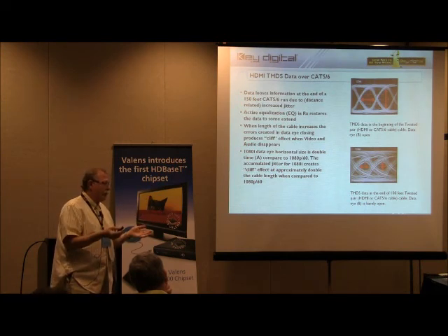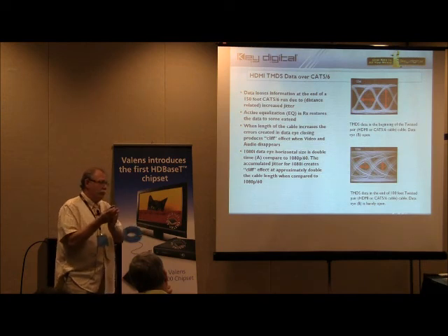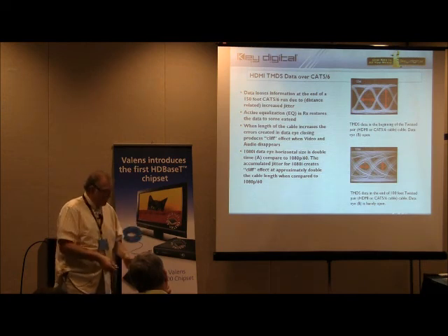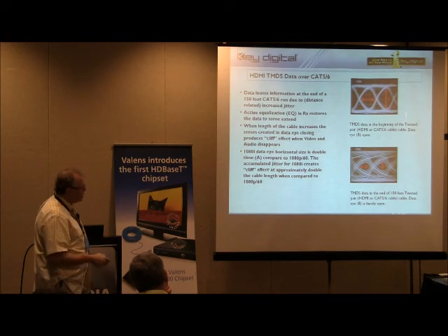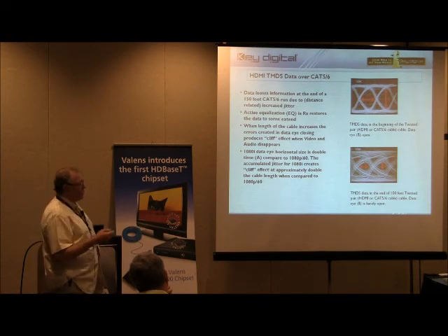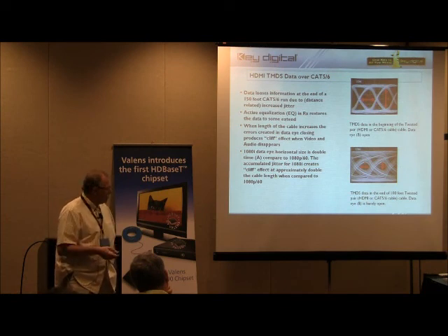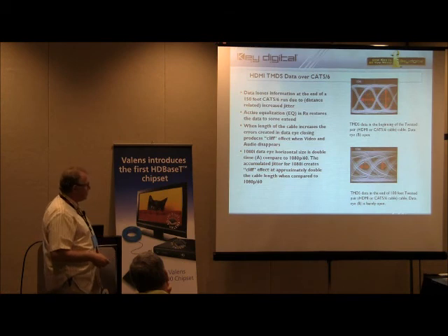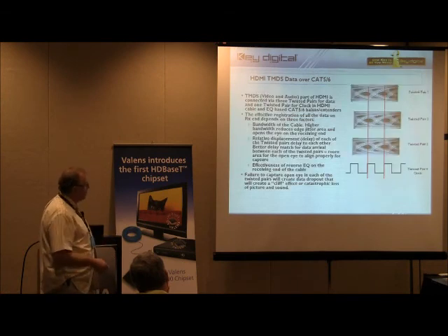So you won't see any quality degradation until the point when your data eye is closed, and then the data drops and you see nothing. So that's one of the very practical considerations for anybody using twisted pair or HDMI cables: stay away from the cliff. Don't fall over. And that's very important, because if you fall over, then there's no data.